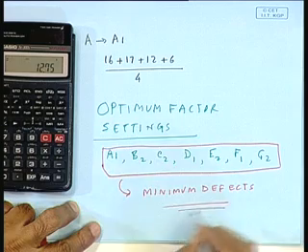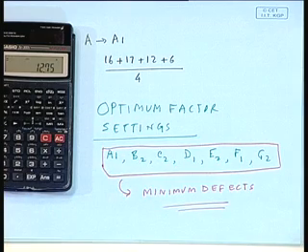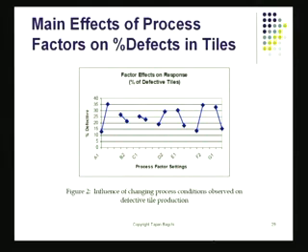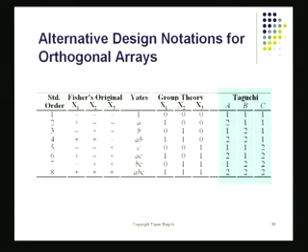And that would be done in what we call a verification experiment. And this was done basically by Taguchi. This was done once the data was complete. It was done this way. This is a great example where a simple experimental plan was used, and he has accomplished a lot. In fact, he was able to reduce the defects from a pretty high level to a pretty low level just by manipulating the factors in a way that would be guided by this OA, the orthogonal array, and he was able to do that.